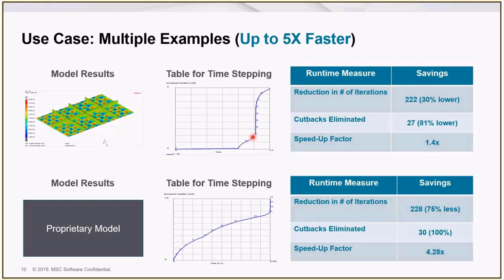We can see that we were initially able to run a fairly small number of increments of a fairly decent size, and then there was a transition period, and then we had to run very, very small increment sizes, a large number of them, and then we were able to open up again and have each increment with some respectable amount of load improvement.